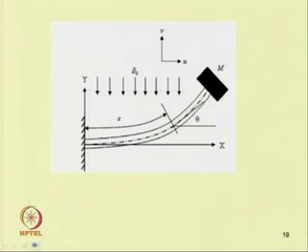So, as an assignment, one can take the system. Let the same cantilever beam be subjected to a magnetic field. In this case, how to determine the equation of motion? One can also consider the effect due to this magnetic field. If one takes a small element on this beam, if this beam is a conducting material or magnetoelastic material, then it will be subjected to a magnetic load in axial direction, and in addition to that it is experiencing a couple.